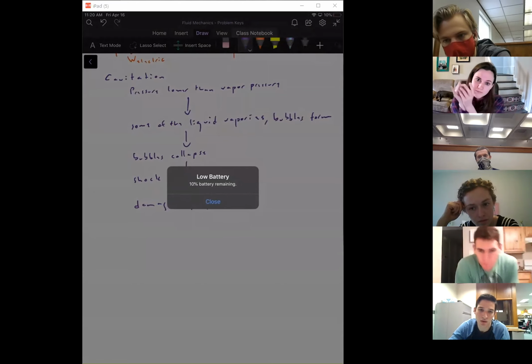In this case, we would say point 1 and point 4 both have velocities of 0, but there has to be a velocity going through the pipe or else it wouldn't be moving from the first tank to the second tank. So the velocity at point 1 can be 0, and V2 is equal to V in pipe. And so is V3 if it's a constant diameter pipe. That's the velocity that causes the loss. That's the velocity we would use when calculating the head loss. So even if point 1 and point 4 both have a velocity of 0 in our mechanical energy balance, there's some velocity in between that causes a head loss.